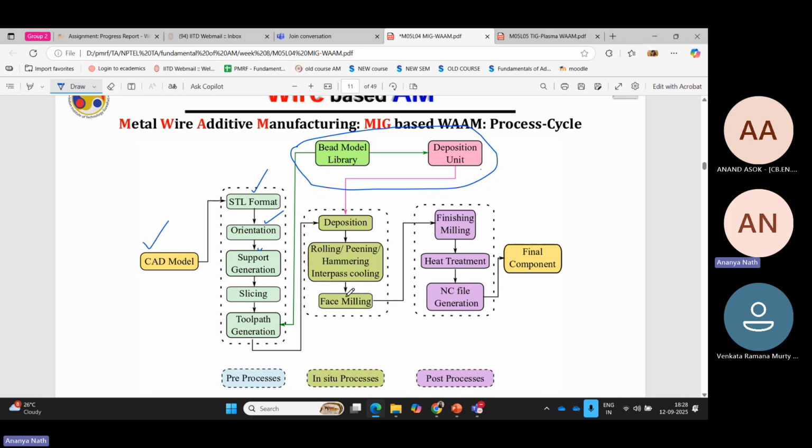By that time, you will also change the tool from additive to subtractive. The build plate will go to the other side of the machine and it will also take some time. So if you continuously feed the argon gas, the problem will eventually be solved. But it's a good question that you asked. Did you get the answer?